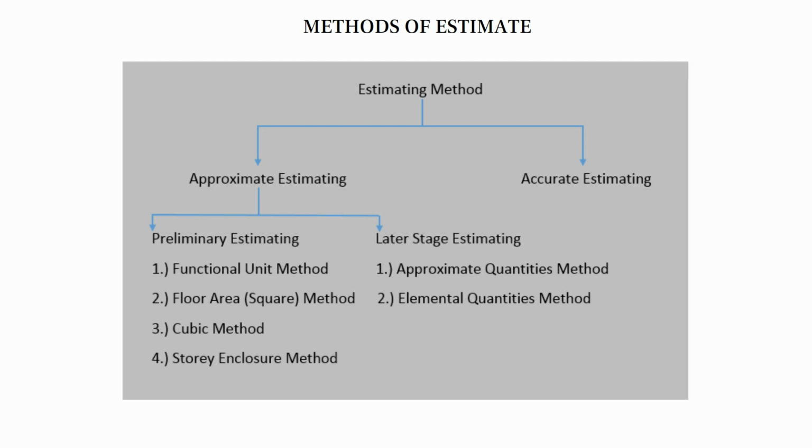During preparation of the estimate, detailed surveying, design, drawings, etc. are not required. This estimate is prepared after preliminary investigation, preliminary survey, and where required subsoil investigations and tests to determine the safe bearing capacity may be conducted. A line sketch of the proposed project according to its requirement may be required. Rates are determined either from practical knowledge or from records for similar work.